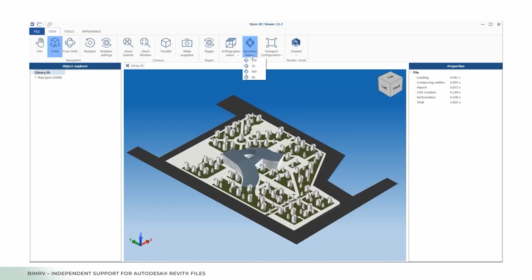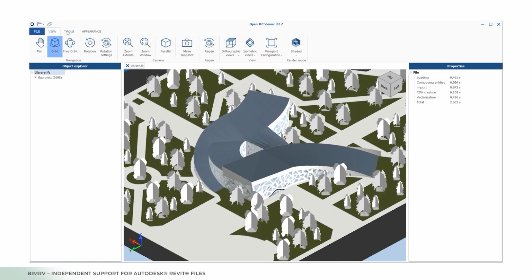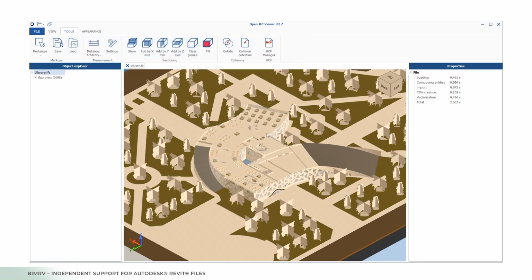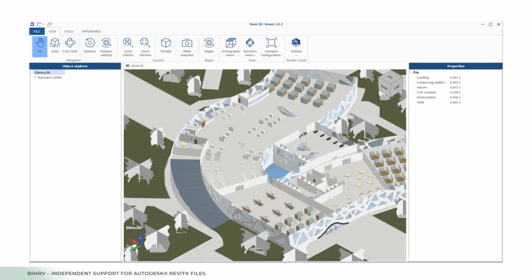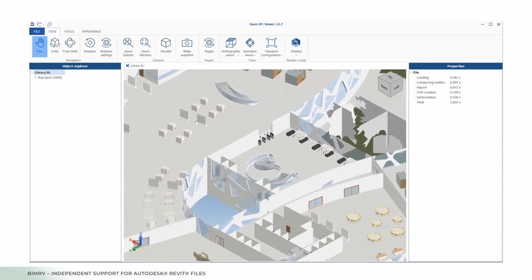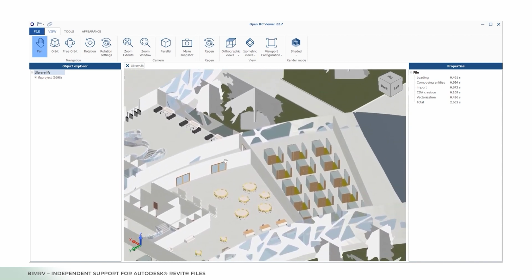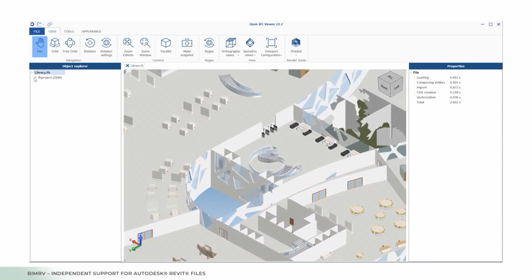We implemented export of project information, measurement units, building, construction site, collection, and translating levels for IFC. We can convert all geometries of elements and materials. For each element, we get visible geometry by settings, translate it, and modify. We have to modify it because geometry representation is different in two file formats.